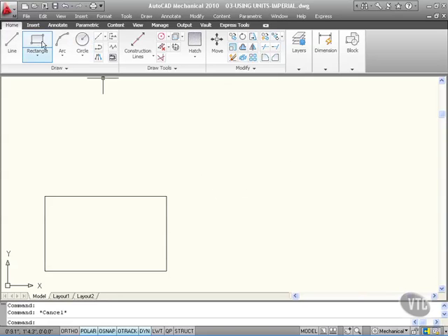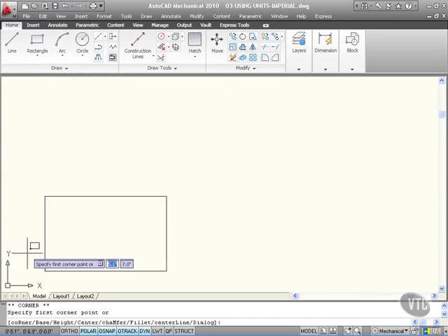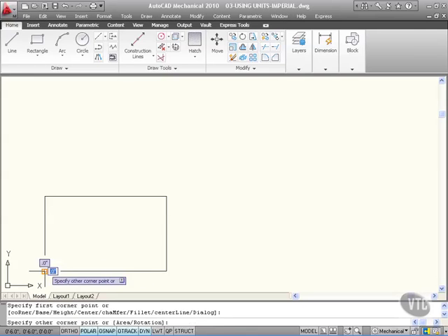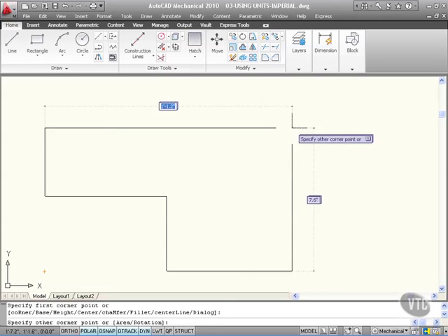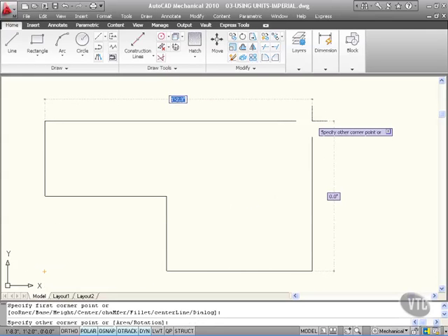So now I go to rectangle again, and I'm now going to click on this corner here. I'm going to use the object snap, the endpoint snap. So when I hover there and click, like so, and come out now, can you see, look, as I get bigger there, it automatically goes to that 1 foot, 2.3 inches in the X direction. Now to type that in, I'd put 1, and then I put that symbol there like that, then a dash, and then 3 inches, like so.